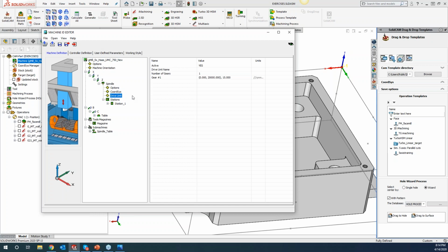That's where this really comes into factor as well, because it can look at all the different stations that you have in here, and based off of when you are picking your main spindle or your sub spindle, or your upper turret or your lower turret, it's going to look in your VMID file and pull all those numbers in there for you. Did I explain that right, Greg? Or did I explain it where it makes sense?